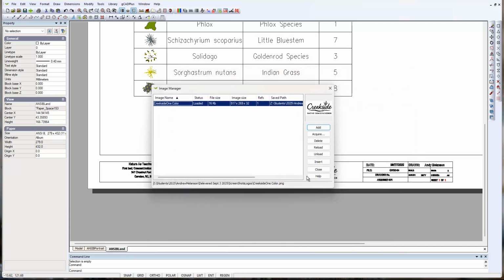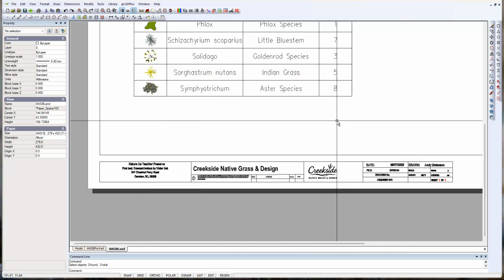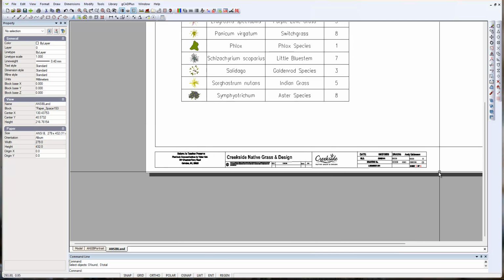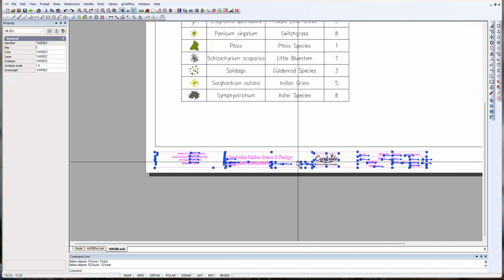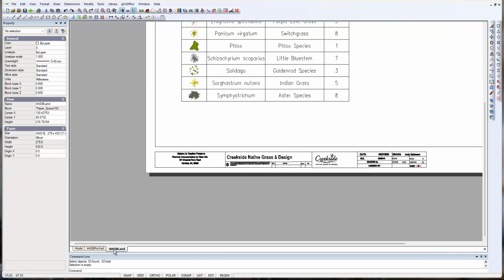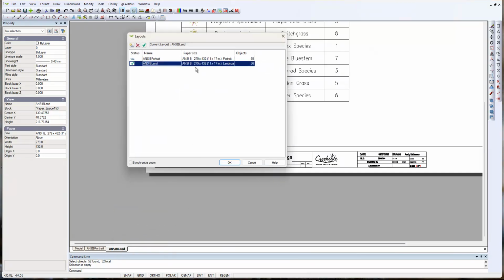So let's return to the question now, which was, how do you turn this information that you got into a block? It's a relatively straightforward process. Just put a window around everything in there and then turn that into a block. What I would do before doing that is look at my layouts manager just to see the size that we're going to work with.